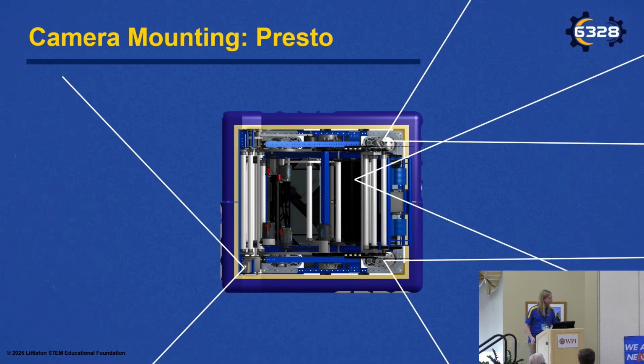And here's an example. So this is our 2024 robot. We have a bunch of cameras on the front for tracking the speaker, but that back camera is positioned specifically to increase the total field of view of the vision system across all of the cameras. We want to make sure that we're tracking April tags even imprecisely, regardless of the robot's orientation or position. That back camera is actually a wide-angle lens, so it's about 90 degrees. Good example of how you shouldn't be afraid to mix up camera lenses and types based on the requirements.